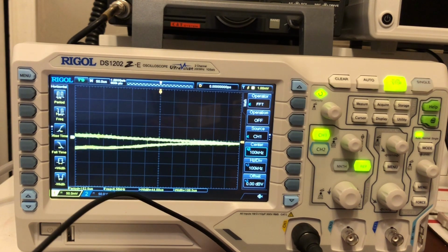For rectangle, you're measuring transient or short pulse where the signal levels before and after the multiplication are basically the same, such as sine waveforms with the same amplitude and rather similar frequencies. Then you can measure wideband random noise with waveform spectrum changing relatively slowly. For Blackman, you use it to measure single frequency signals or search for higher order harmonics. In Hanning, you use this for sine, periodic, and narrowband random noise. In Hamming, you use it for transient or short pulse where the signal levels before and after the multiplication are rather different. Flat top, you use for signals without an accurate reference that require accurate measurement. And triangle, you use for narrowband signals with stronger interference noise.